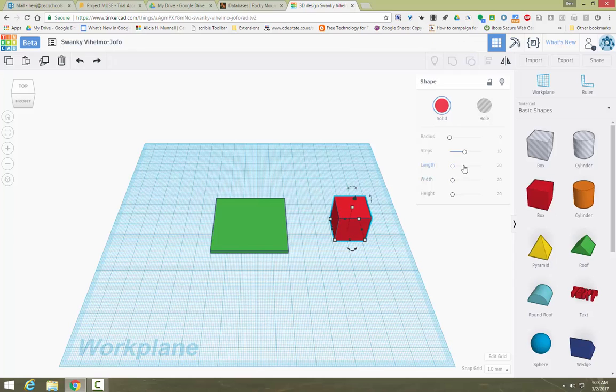I'm going to drag another box out here, and I'm just going to go ahead and again use this. I'll just say length, I'm going to say 50 here. This is going to be a street, by the way. And then the width, I'm just going to say 5, and then for the height, I'm going to say 4, so it'll just be slightly raised, or maybe even 3. So it's going to be just slightly raised above the surface there, and you need to hit enter after you type in these widths or else it doesn't stick. So maybe that'll be a road. If you want to change it to black to represent pavement or something like that, you're welcome to do that.